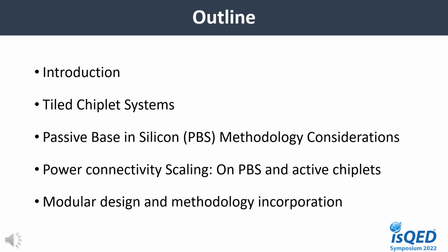At first, I'm going to explain the need for chiplet-based system development while explaining what tile chiplets are and why they are really important. Mainly, this presentation focuses on passive base in silicon or PBS methodology considerations, along with power, connectivity, and scaling of active chiplets on a PBS interposer. I'll also talk about modular design and methodology incorporation using a simple example.